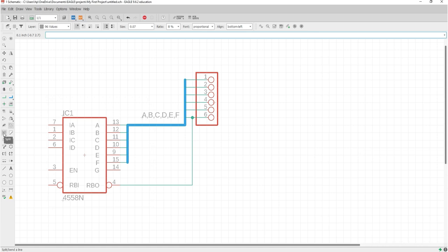After that, this is the split icon. This tool is used to insert a bend into a wire. The next one is miter. It is used to round off or bevel wire joints. The grade of mitering is determined by the miter radius. Positive sign results in a rounded joint, negative sign in a bevel.